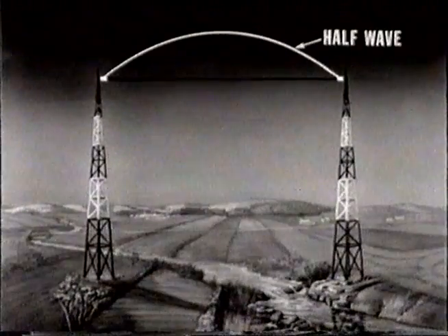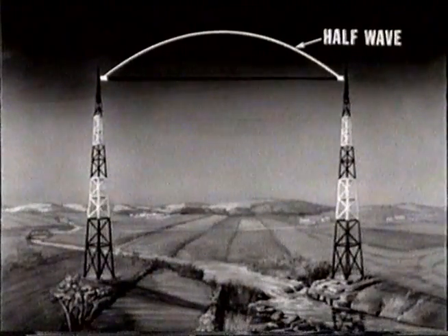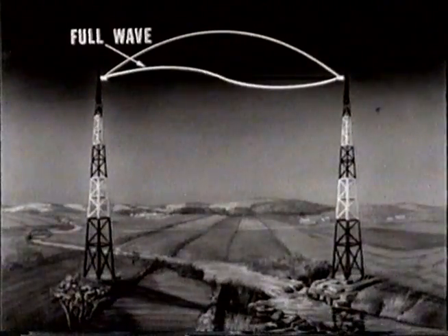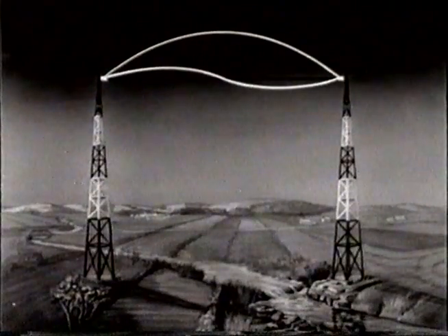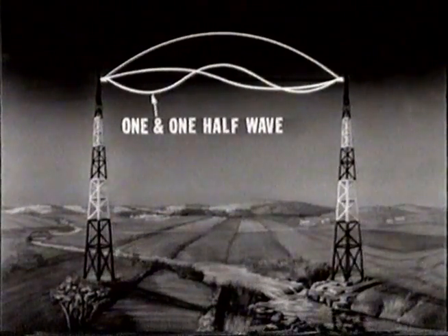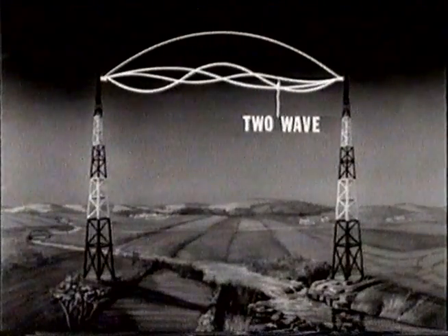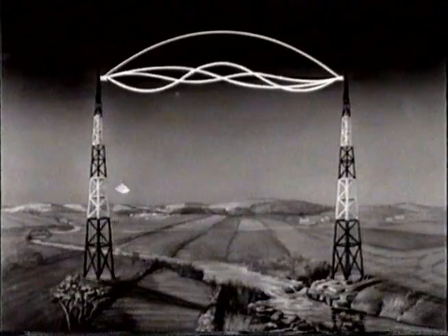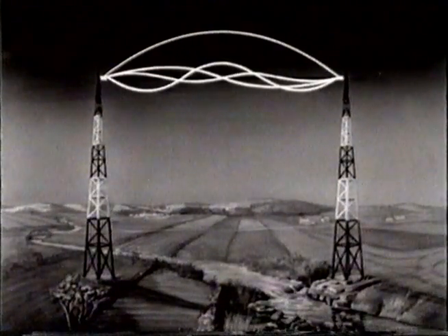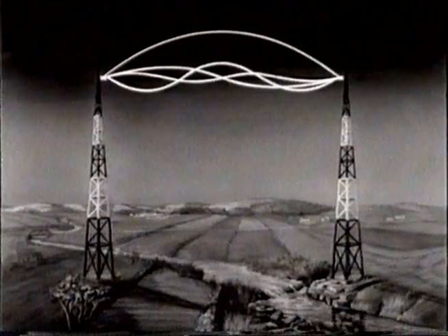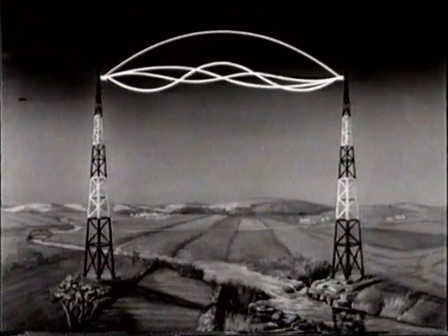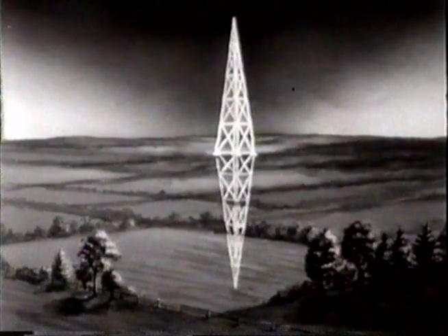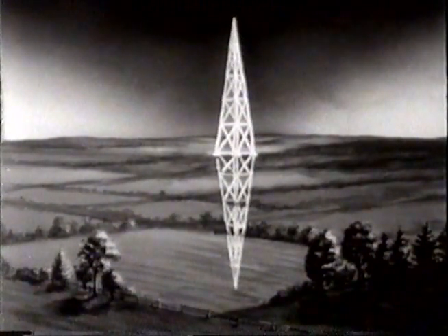The Hertz antenna may be resonated not only by the half-wave, but also by any harmonic of the fundamental. That is, a full wave, 1½ waves, 2 waves, etc. Any multiple of the half wave. In practice, however, the antenna is usually designed to resonate to the half or the full wave only. We may picture a half wave resonating on an antenna.